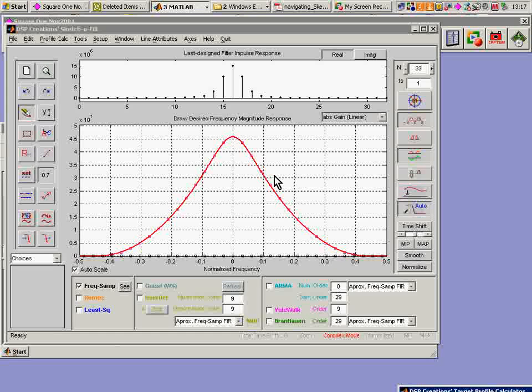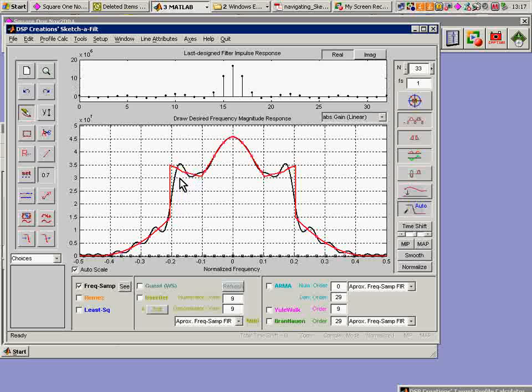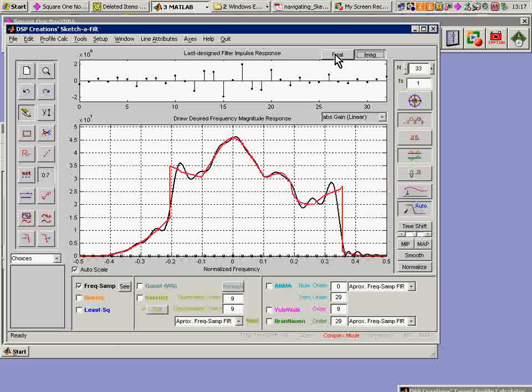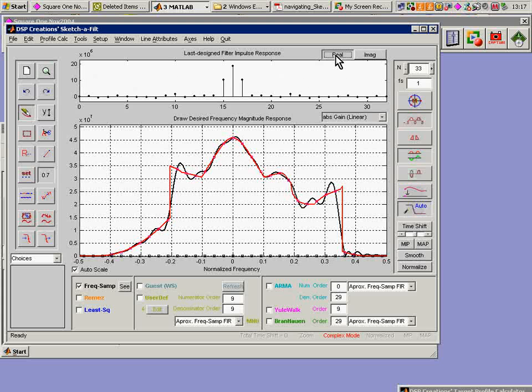I can make complex, as I mentioned earlier, by what's happened now. It's brought it in and it's clicked this off right here. If I click this on, this is the more usual situation. A change here echoes back as a negative frequency change, and I have real coefficients. If this is clicked off and I make a change here and no corresponding change here, then the symmetry is broken and I picked up a piece of an impulse response, which is imaginary.